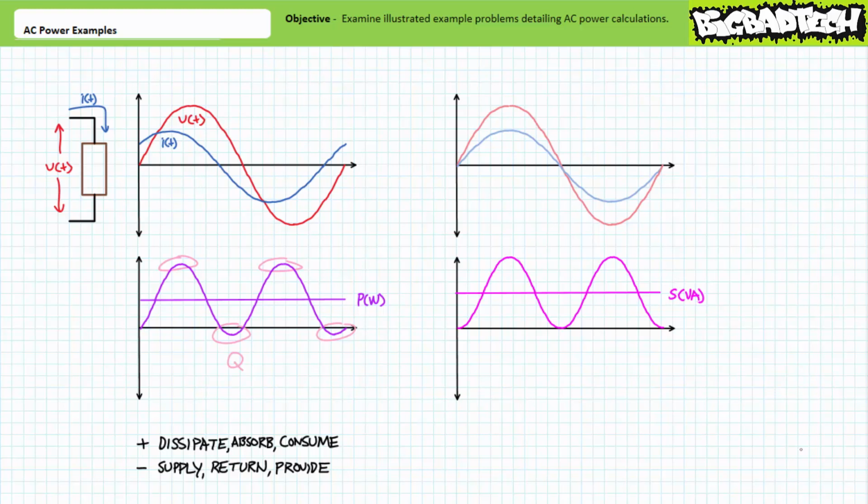Reactive power Q is somewhat difficult to visualize graphically, whereas real and apparent power can be thought of as simple straight line averages running right down the middle of their respective plots. I like to think of reactive power as those periods of negative power, and their matching positive periods, cyclically exchanged between the circuit and the source.